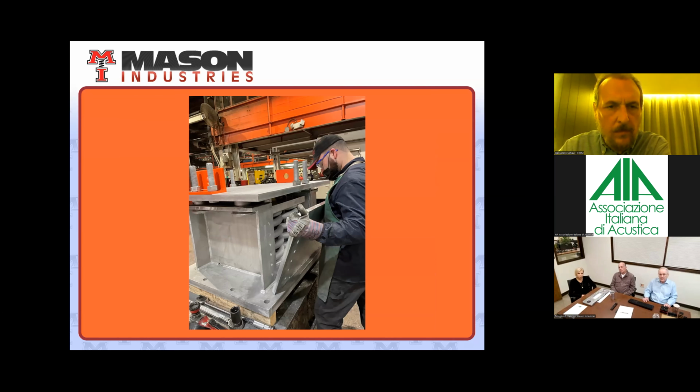This was obviously a very large isolator that supports a helicopter landing pad on top of a hospital in California. So not only were they concerned about the vibration and possible impact of a helicopter landing on top of the hospital, we also had to be concerned with the seismic restraint. California being a very high earthquake risk area, as is Italy. And we'll touch on that later in the seminar.